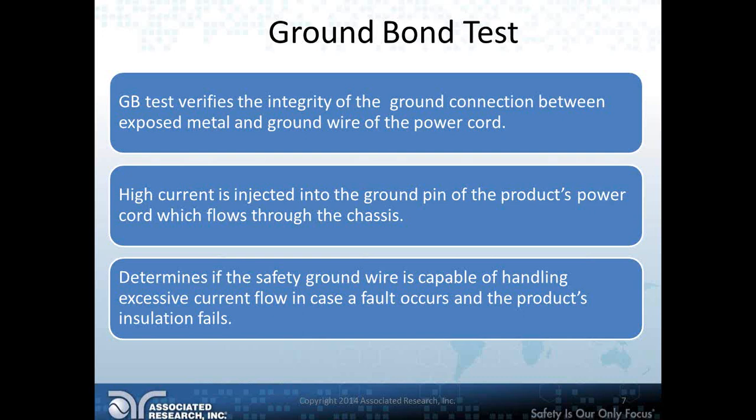By simulating a failure condition and circulating excessive current through the device's ground connection, the ground bond test helps to verify the integrity of the connection to earth ground.